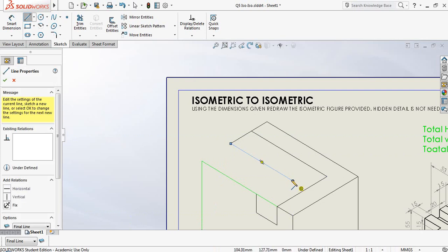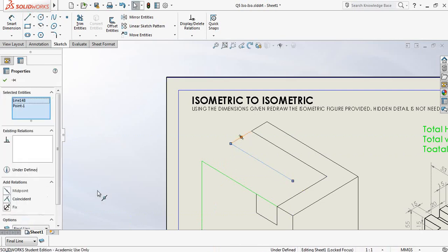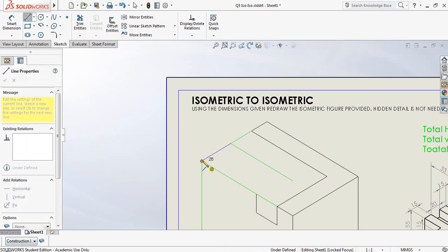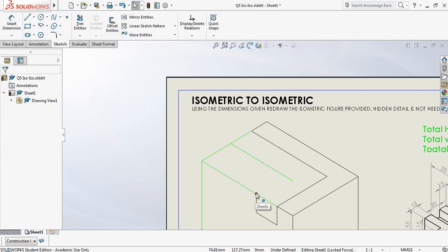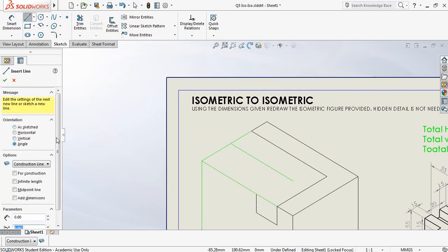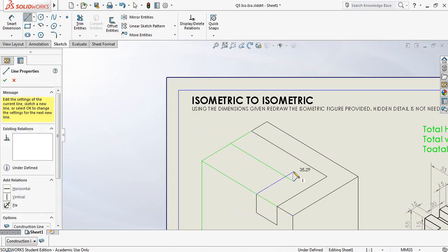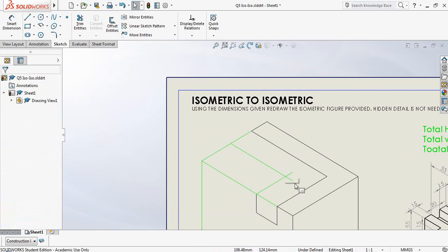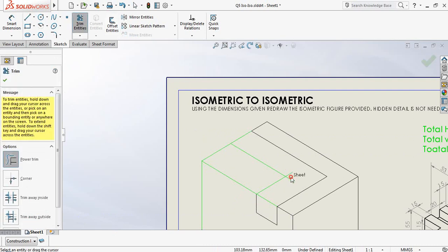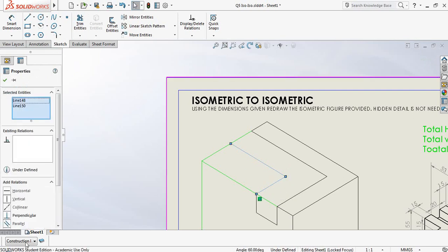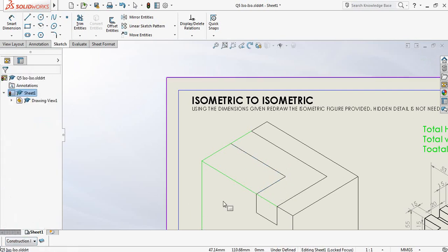down. Right, take note, I'm going to be using my construction lines here yet again. And I want an angled line here at 30 degrees from this point here onward. Okay, we have another intersecting point over here, so I'm just going to clean it up a little bit with my trimming tool, and I'm going to convert this line and this line to a final line.